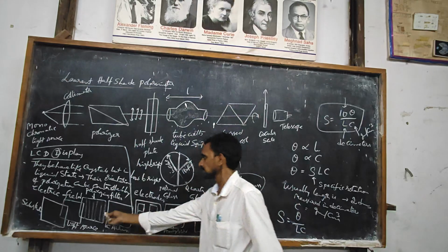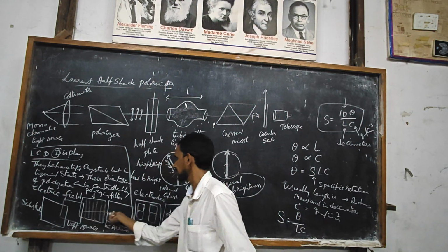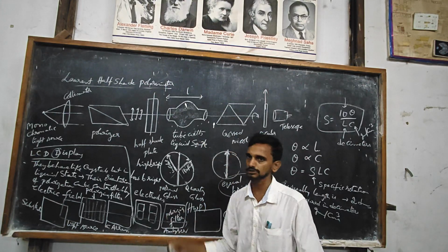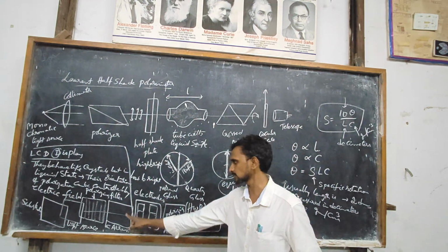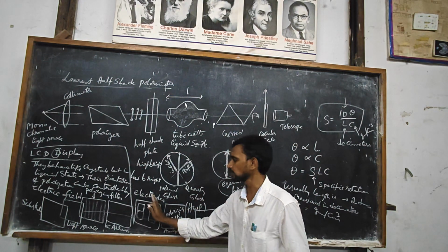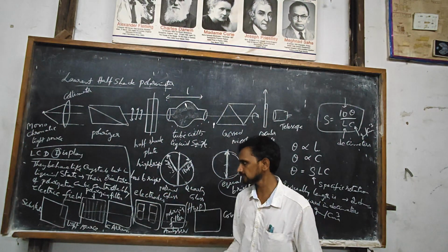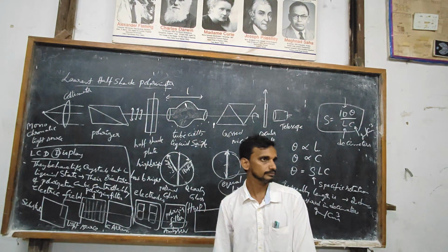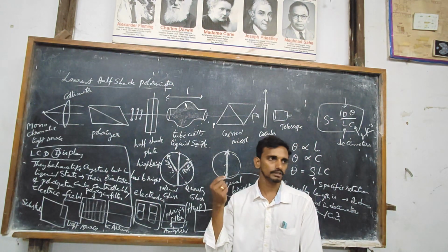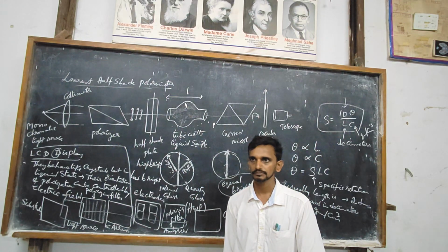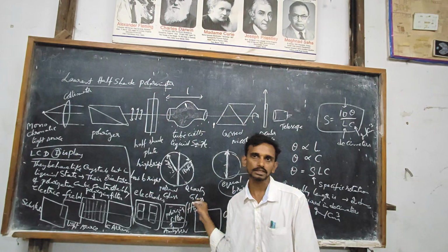So usually the crystals are oriented so that the polarized light directly passes through the crystals without any obstruction. So what happens when you apply an electric field at the location of electrodes, the crystals will get tilted, so that polarized light cannot travel through them. So in those locations we will see a dark band on the glass plate.